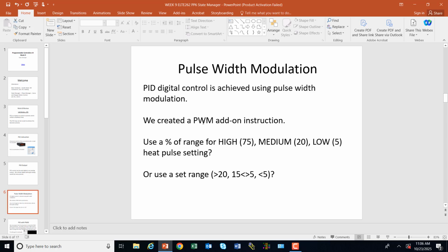Most people liked that, thought it was pretty cool, and I thought it worked well, except for the relay output card that we cooked. It's interesting that I equals P over V, and those were 200 watt light bulbs over 120 volts. So we should have been at less than 2 amps, but that relay output card, one of them we burned out an output. So we're going to try and switch to 100 watt light bulbs.